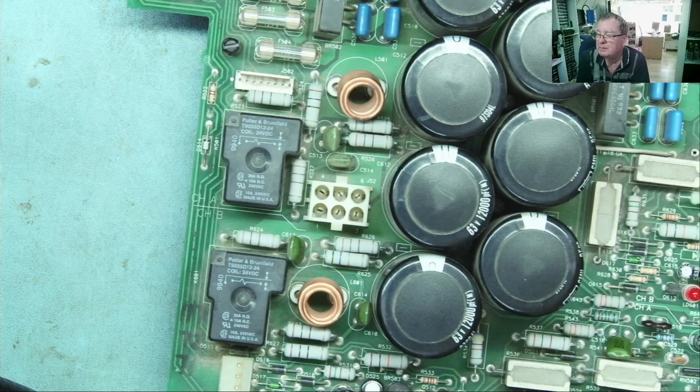So just to sum up, resistors always fail by going high in value. When you measure them in circuit, they may well read lower than the rated value. This is normal. High powered, especially low value resistors, if they fail, burn up, that sort of failure will be caused by something else. So you need to find the cause, a short circuit. And high value resistors around the 1 megohm, especially in things like power supplies and the startup circuit, if they fail, it's probably just the resistor. Just change the resistor and it'll work. Okay, so I think that covers just about everything we need to know about resistors. Let's move on to number 8.